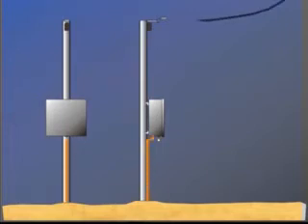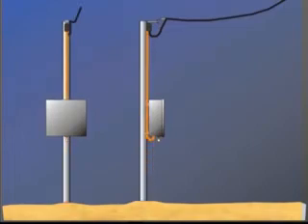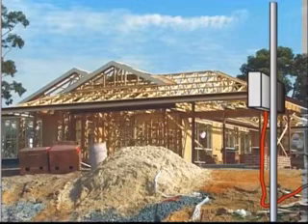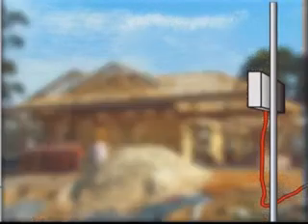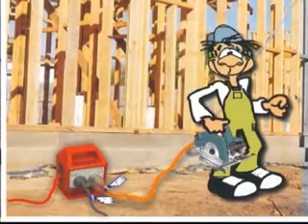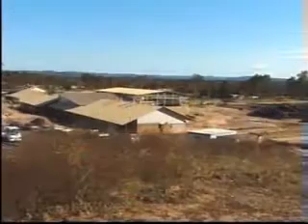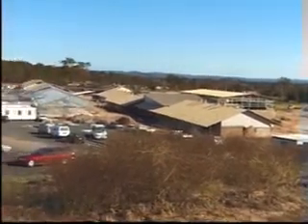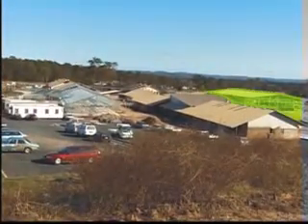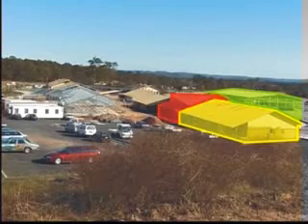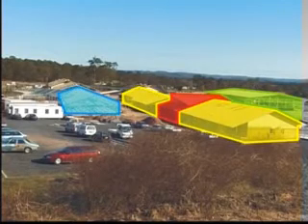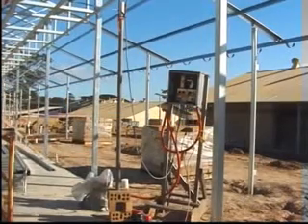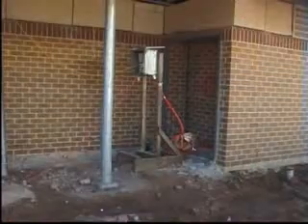On small building sites, power is supplied by extension leads from the main switchboard directly to tools. Larger construction sites are broken up into convenient areas. Each area is serviced by its own sub-board mounted securely on a temporary support. Tools are then operated using extension leads from the sub-boards. Sub-boards must be isolated and all boards locked at the end of the workday.